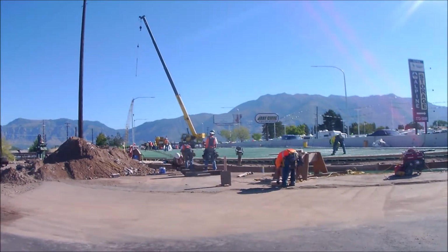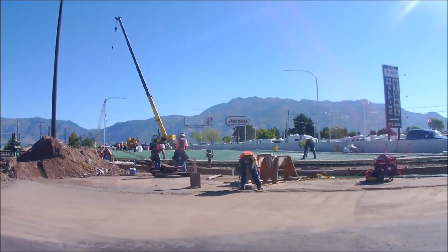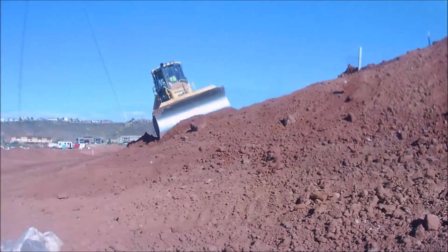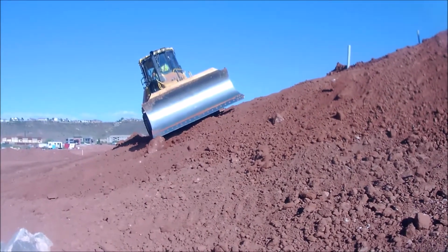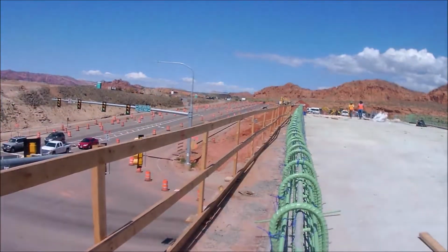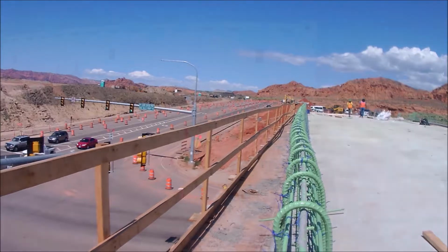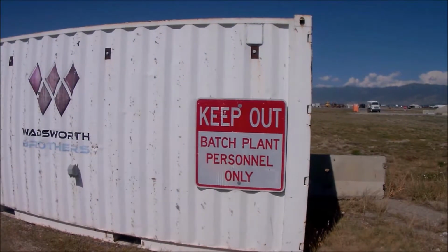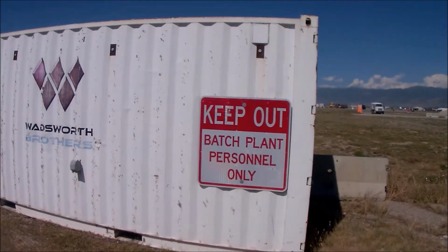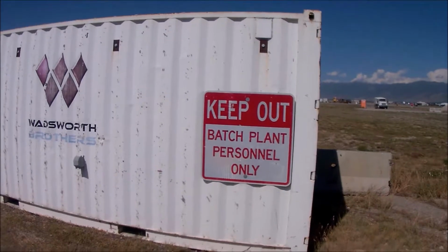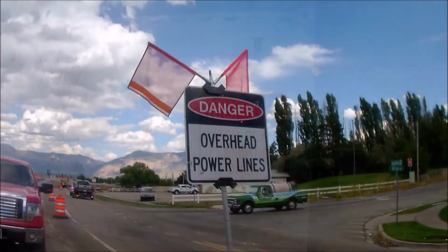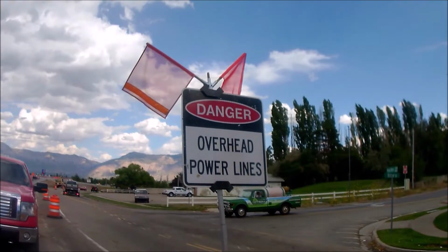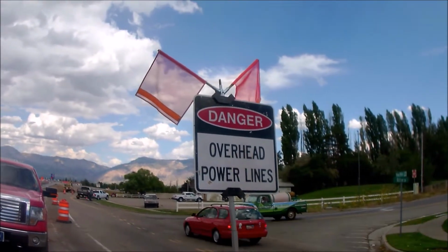Clear snow and ice prior to starting work activities. Maintain lighting if darkness falls or weather conditions change. Control dust. Maintain electrical cords. Properly dispose of trash, scrap, debris daily. Keep signage and other reflective communication devices clear of dust, dirt, graffiti, or other obstructions that will impede their effectiveness.